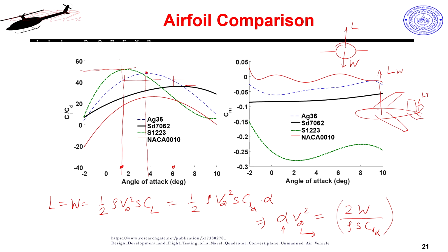Well, we will not go into stability right now. Yes, it does affect the stability, how the CM changes, but we are not worried about that. We are saying my craft is either stable, or anyhow I have an autopilot. Even if my craft is slightly unstable, I can make it stable by using my autopilot, which gives me some additional damping. So, it is a stable airplane, but what role does the pitch moment of an airfoil play for the overall airplane's equilibrium?